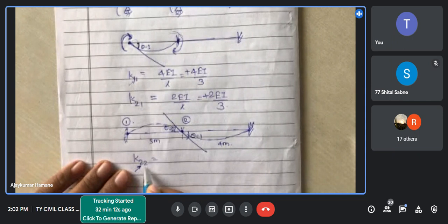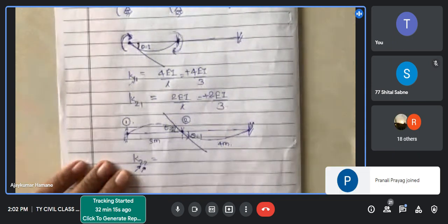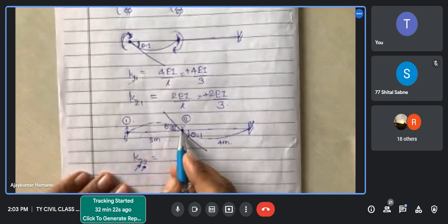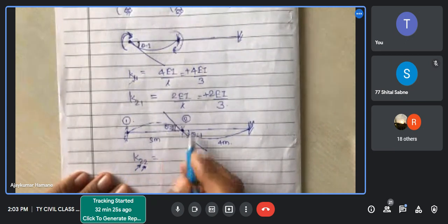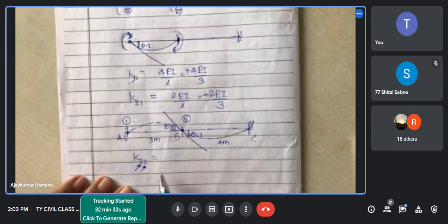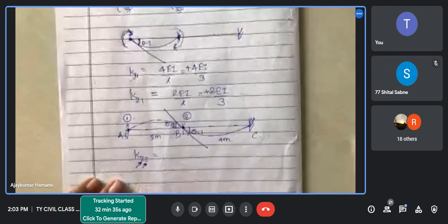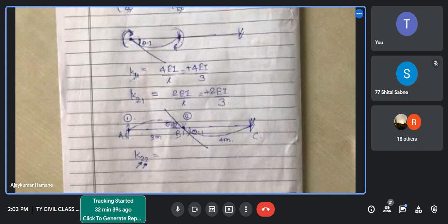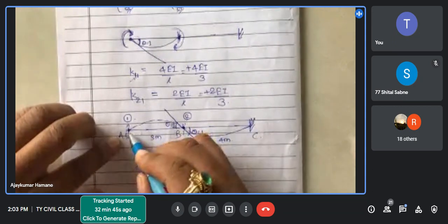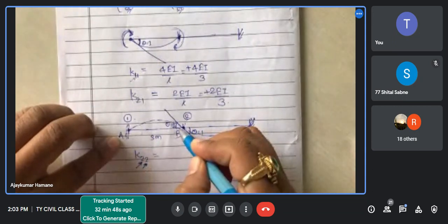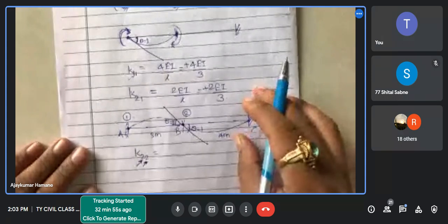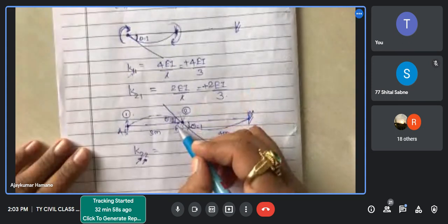That is, what is the moment at 2 due to the displacement at 2. We have a rotation at coordinate 2, and this rotation acts on beam AB and on BC. For BA, how much? Yes, the other end is fixed. The rotation at one end, when the other end is fixed, what is the near end moment? What is the moment at this end? What is this moment?